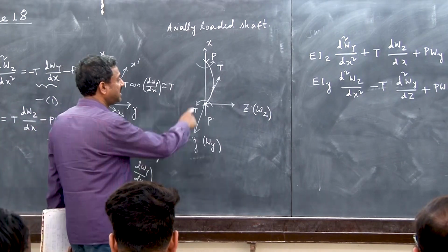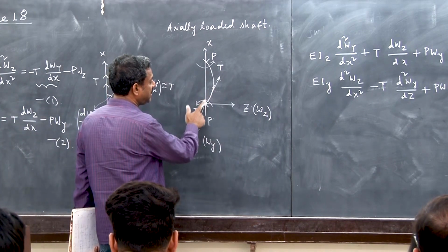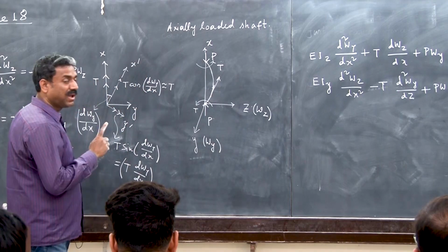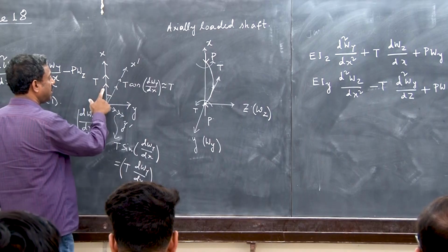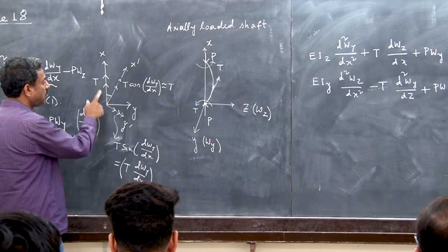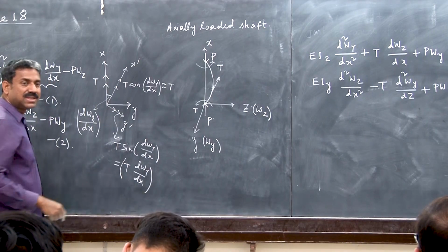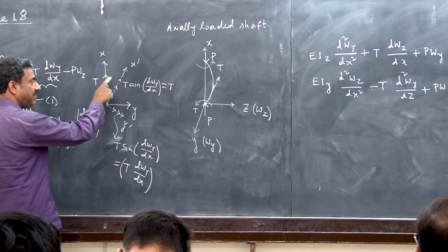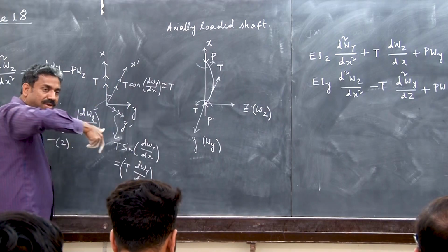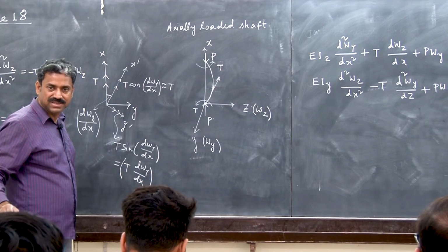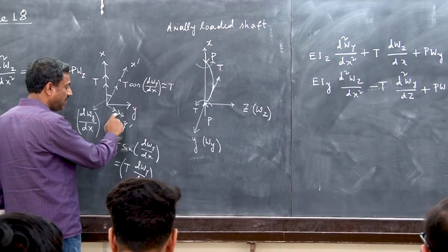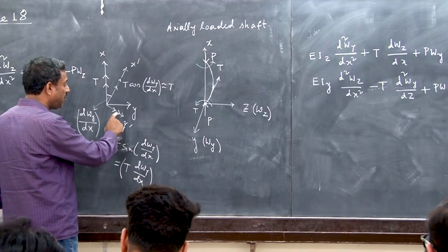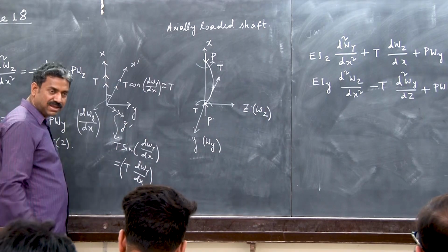When considering the deformed configuration, if I cut a section, I resolve the torque into two components, considering the deformation to be small. Even in the deformed configuration, along x the moment will basically be torque, right? But with respect to the other axes, whatever moment comes will be bending moment.